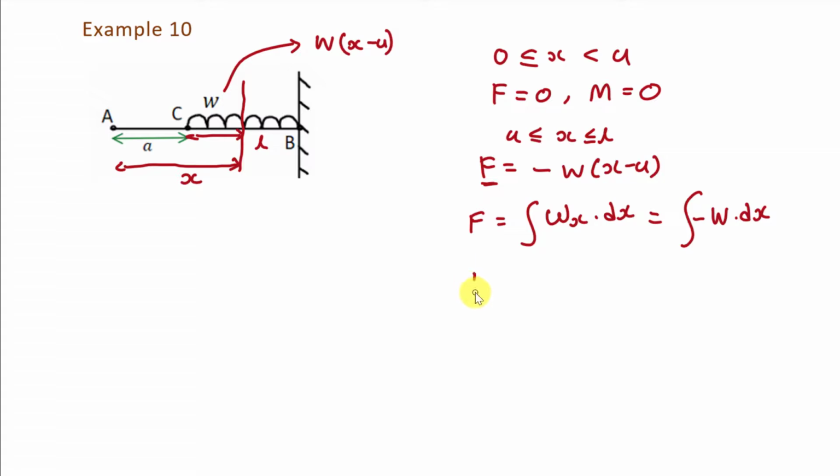So what will be the shear force? It will be minus Wx plus C, and here C is the constant of integration. Now we will find the value of the constant by putting in the boundary condition. Now what is the value of shear force at point C?